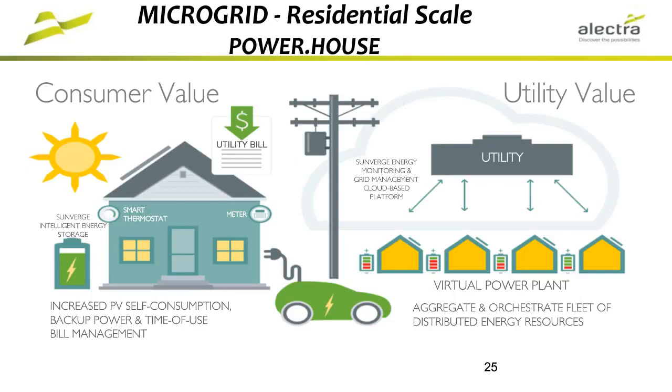This really starts to get into the definition of what we believe to be a virtual power plant, which aligns pretty well with some of the definitions you've heard earlier today. This is along the control and dispatch layer of the architecture with some optimization, what I would call co-optimization, in order to share benefits on both sides of the meter. So these units were a fleet of utility-owned assets within our service territory, but we allowed the customers to retain 50% of the battery capacity, and we would leverage the other 50% to exercise the units to showcase how they could contribute to distribution level network benefits.